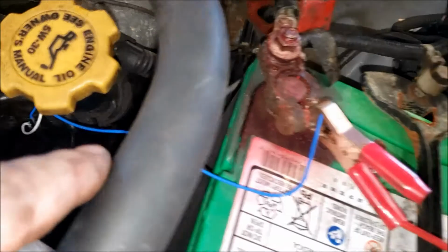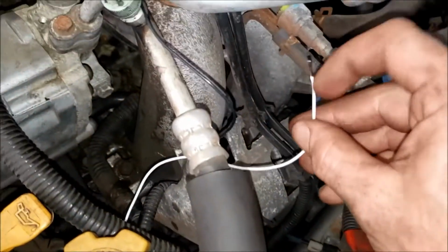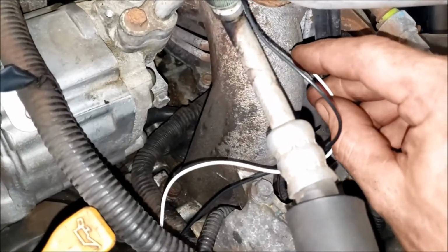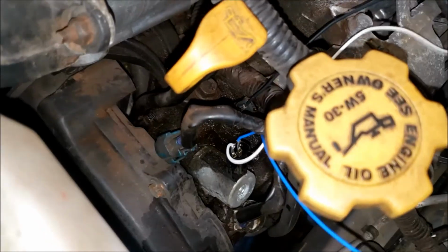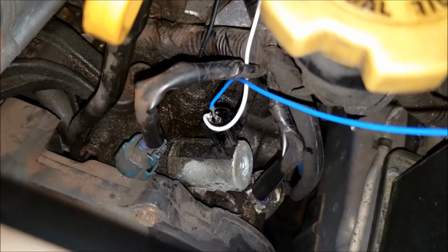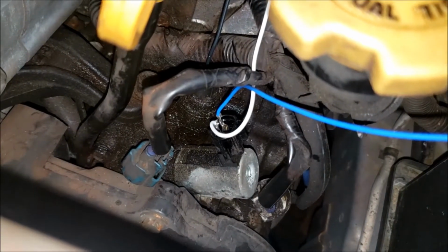So with the blue lead hooked to our battery positive voltage, I'm going to take the white lead and hook it to ground, and we should hear a click. I'm just hitting it right on the intake here. Let's listen for that click though. All right, so we know the solenoid is working. In case you're wondering, you can hook that up in any polarity direction. You're just energizing a solenoid in there.